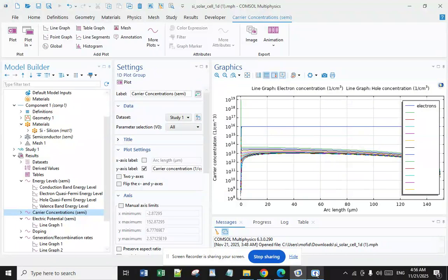Photovoltaic materials become more efficient as the light becomes more concentrated, so the highest overall efficiencies are obtained with CPV cells and modules. However, more expensive materials, manufacturing techniques, and the ability to track the movement of the sun are required. So demonstrating the necessary cost advantage over today's high-volume silicon modules has become challenging.